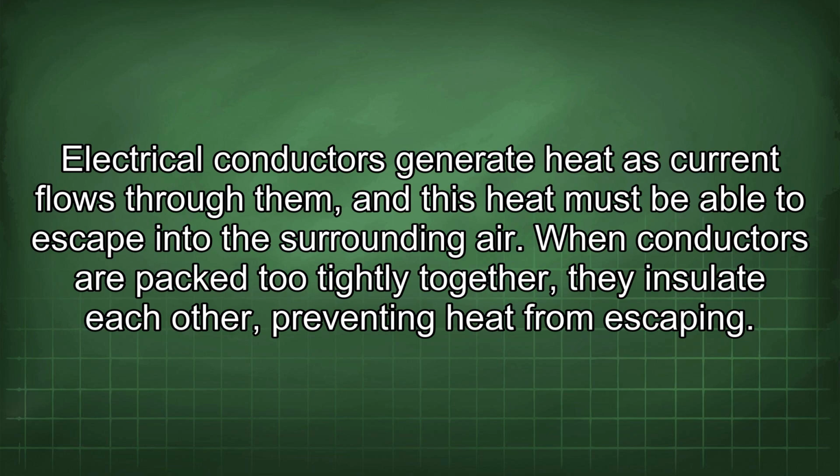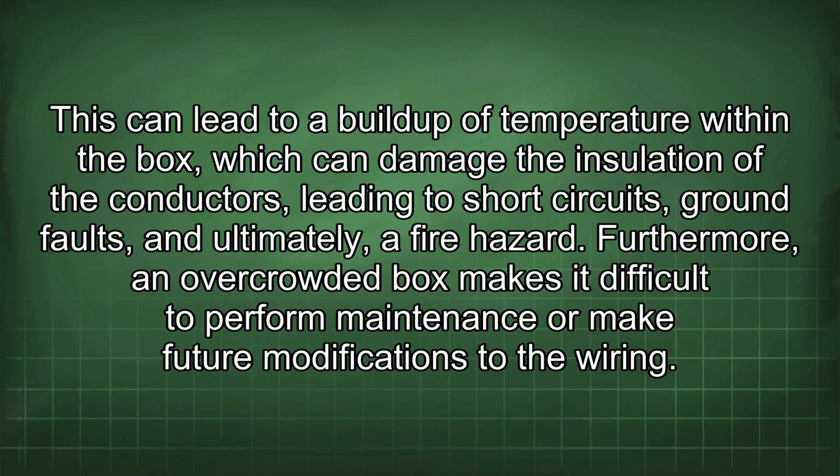Electrical conductors generate heat as current flows through them, and this heat must be able to escape into the surrounding air. When conductors are packed too tightly together, they insulate each other, preventing heat from escaping. This can lead to a buildup of temperature within the box, which can damage the insulation of the conductors, leading to short circuits, ground faults, and ultimately a fire hazard.